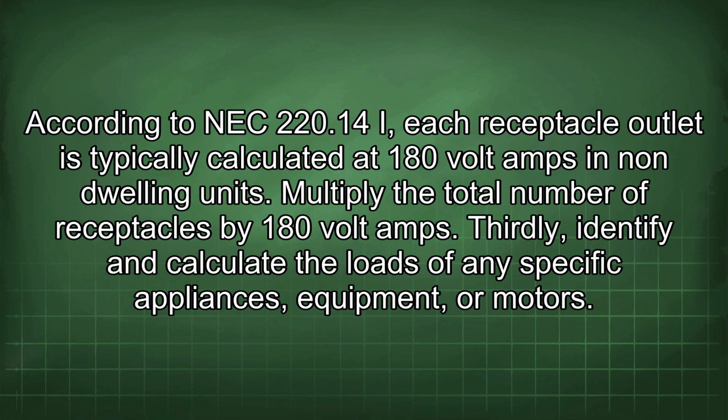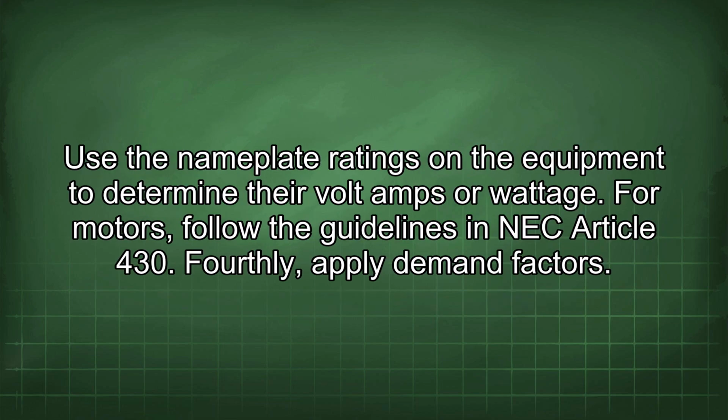Thirdly, identify and calculate the loads of any specific appliances, equipment, or motors. Use the nameplate ratings on the equipment to determine their volt amps or wattage. For motors, follow the guidelines in NEC Article 430.